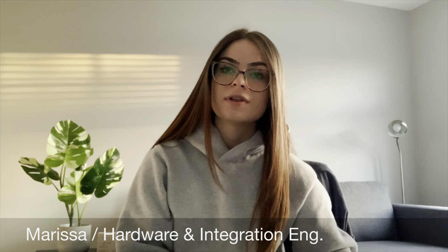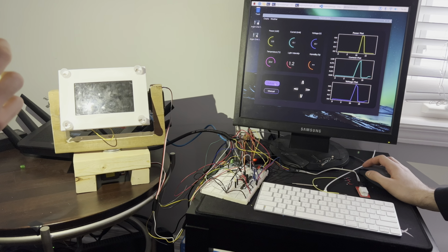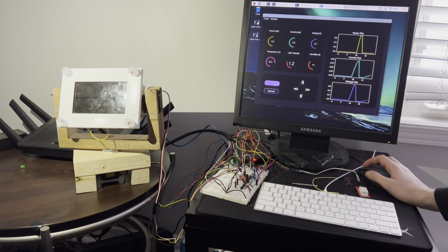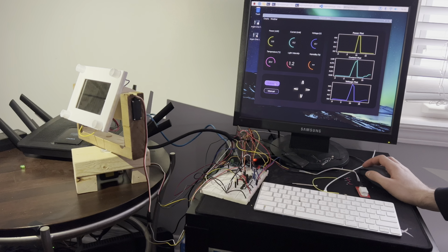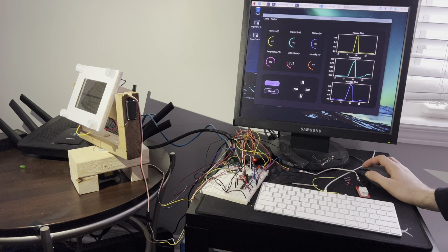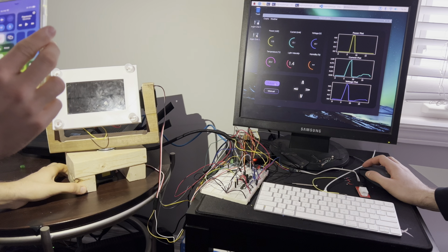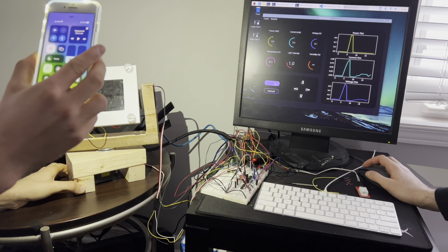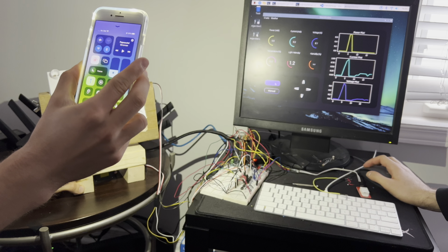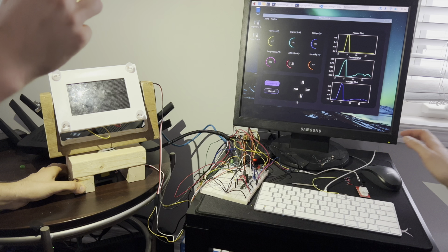For the purpose of proof of concept throughout this demonstration, a flashlight is used to represent the movement of the sun. The system is first turned on, the solar panel is set to be in automatic mode. As you can see, as the flashlight is moved from left to right or up or down, the solar panel tracks it. However, since the LDRs produce an analog output, an ADC was required. Specifically, an MCP3008 was selected as it uses SPI interface which is compatible with the Pi.